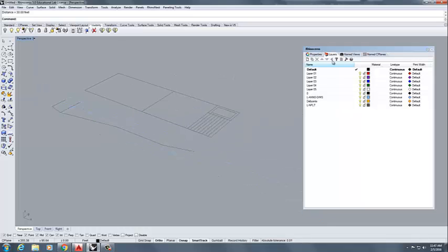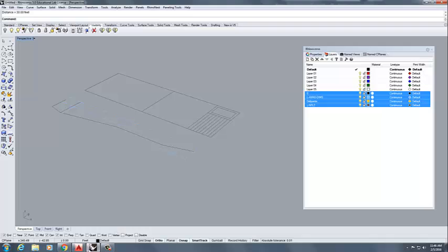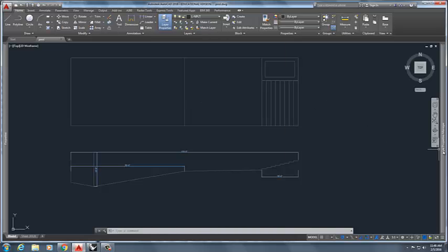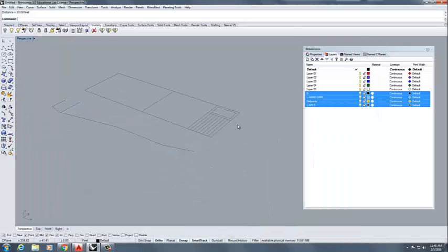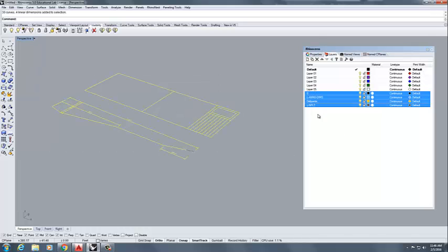In a new file, you'll start to see there are just a bunch of really default layer names, because I still have my layers open. It's default through layer 05, right? Also, it has a 0 layer. Actually, the 0 layer became imported. These 4 layers all came over from AutoCAD. When I open up my AutoCAD file and look at my layers, I have 0, depth points, L anno dims, and L no plot. So that's where these new layers all came from.